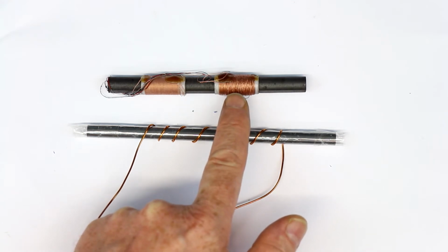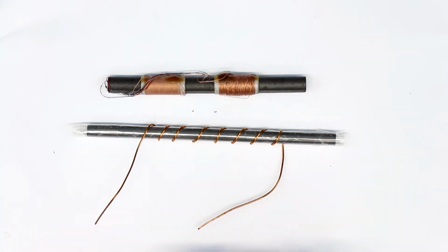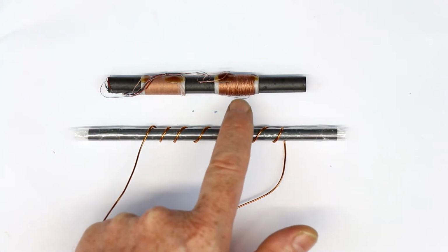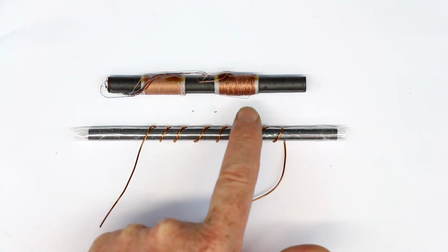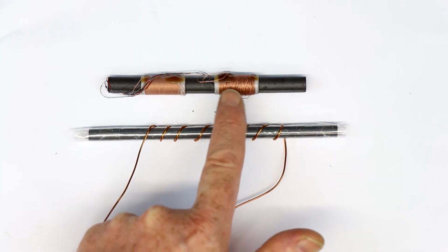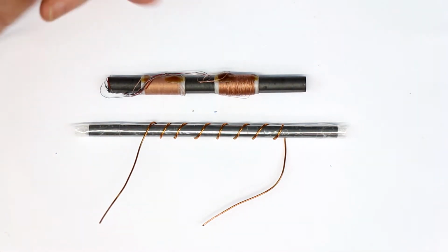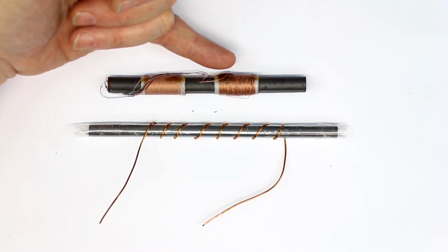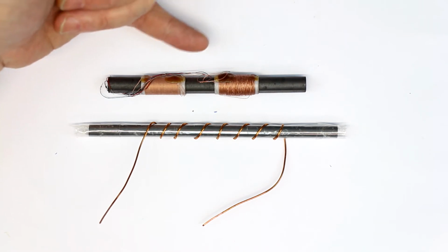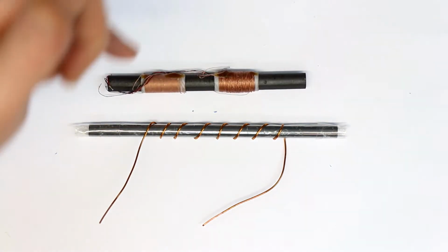That's because for the lower frequencies of the long wave range you need more turns, and you only can get this on a short Ferrite-Rod with multiple layers above each other. And that's the first limitation. Our spreadsheet cannot deal with multiple layers. It is only designed for single layer coils, like here the medium wave coil.